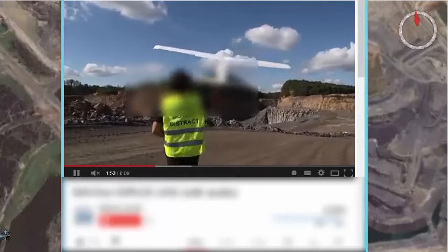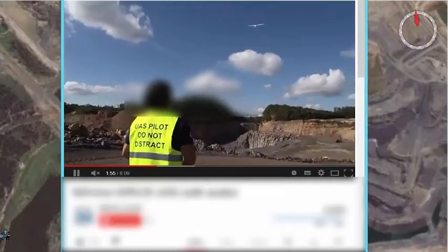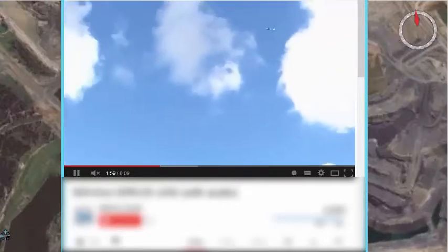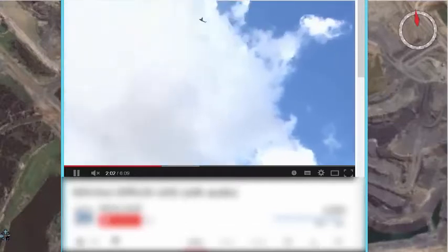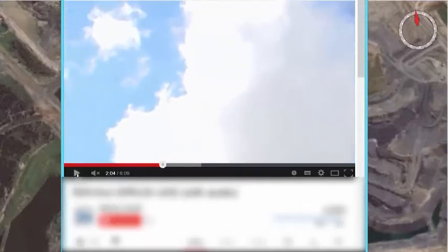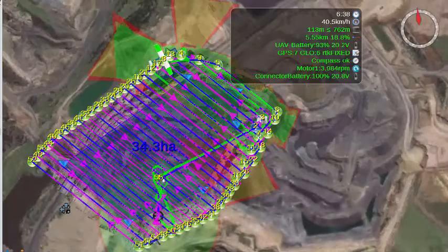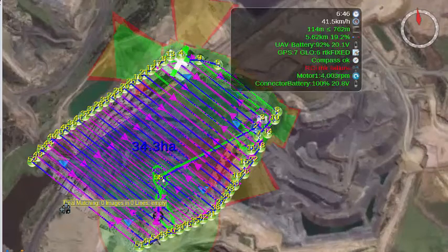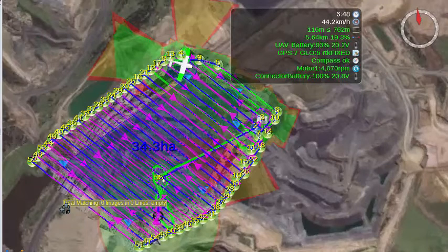The plane is launched from the hand and cruises up to the determined height to gather information to satisfy the ground sampling distance for the area of interest. The plane then follows the flight plan, taking photos at nominated distances to achieve the overlap required for forward, rear, and side photography.